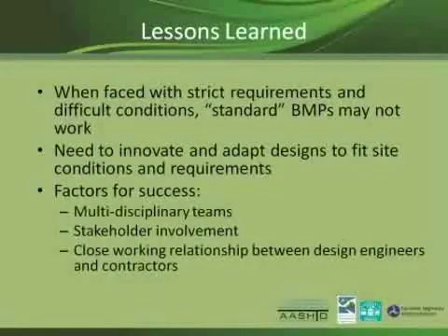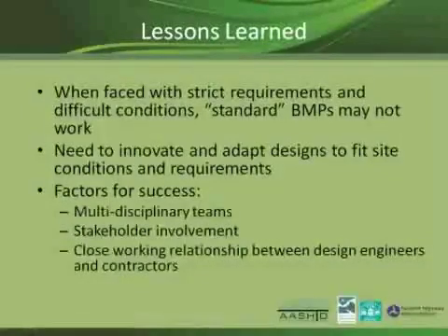So the lesson learned here in Washington is we are facing a really stringent requirement, probably more stringent than other state DOTs due to this issue. And most of our projects are located in a highly urbanized area, so there are not many BMPs that we can use in our stormwater menu. So we are forced to come up with a custom-made BMP.